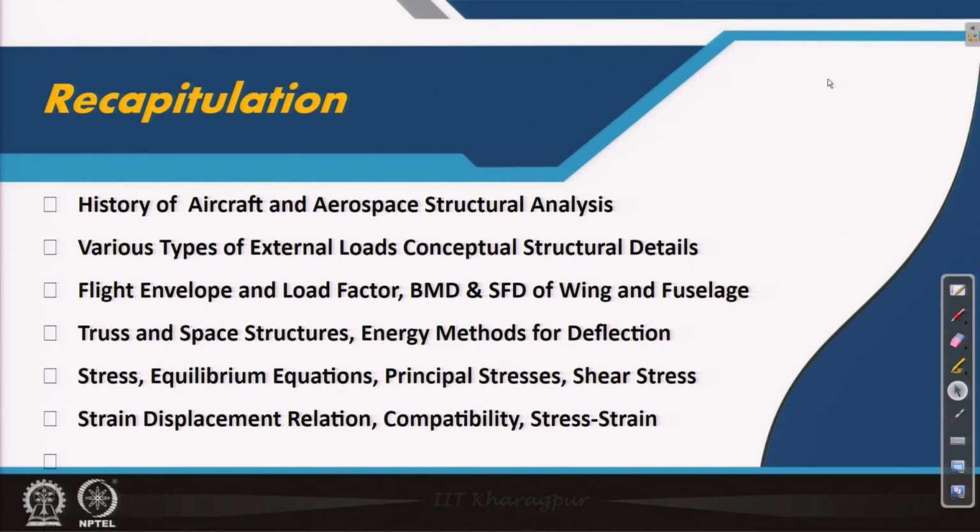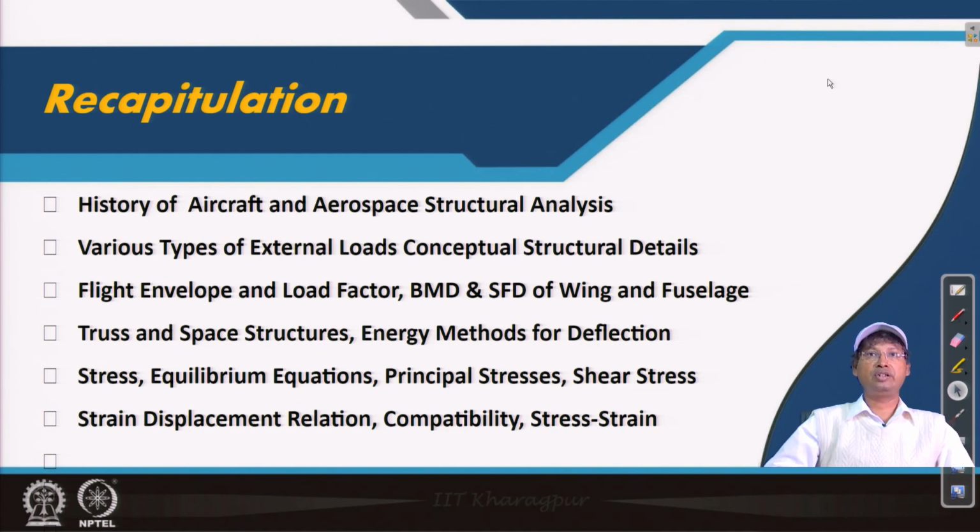After that we have discussed various types of loads experienced by our structure, the aircraft structure. In different conditions it experiences different types of load. When it is airborne, it is not only the loads coming from air and the engine it experiences, it also experiences body forces or the inertia forces because of the movement, the maneuver we say. So, for maneuvering, different types of g forces come, and that is popularly known as how much g it can withstand or the body force it is experiencing.